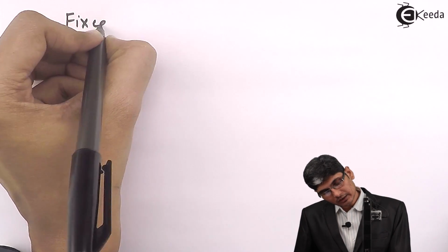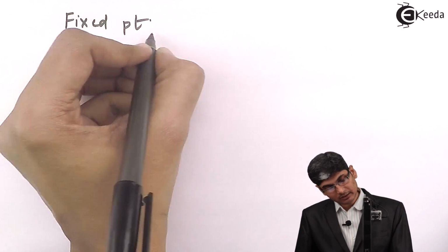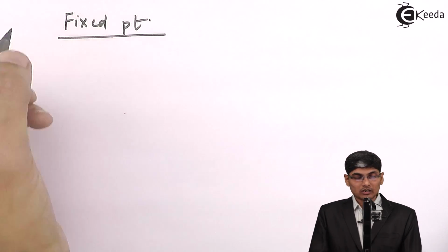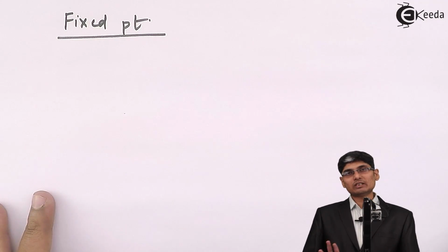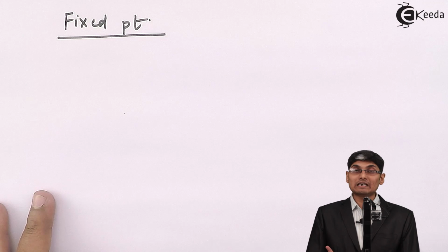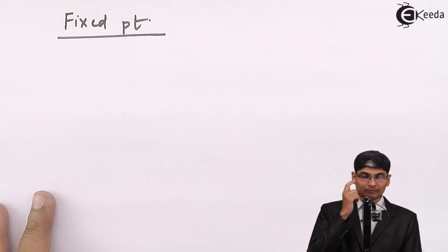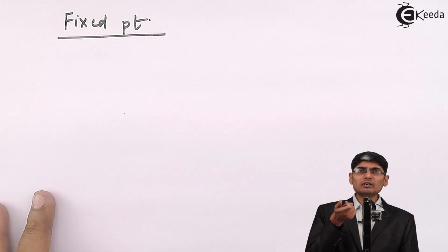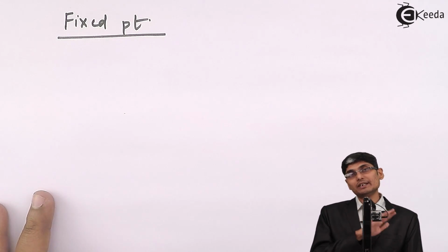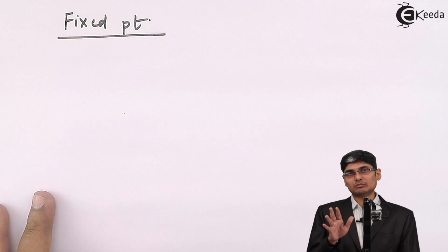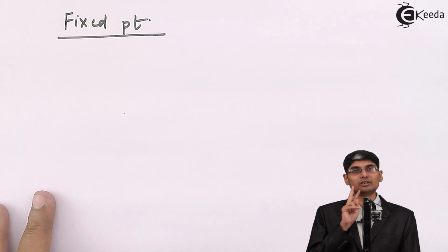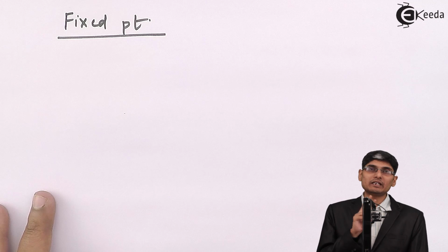In fixed point number representation, because in DSPs we normally use additions and multiplications, I will be only concerned about the numbers which will undergo addition and multiplication, because those are the only two processes that we use while implementing a digital filter.